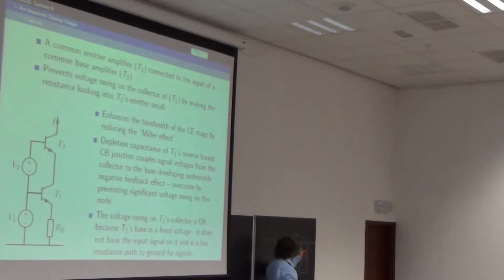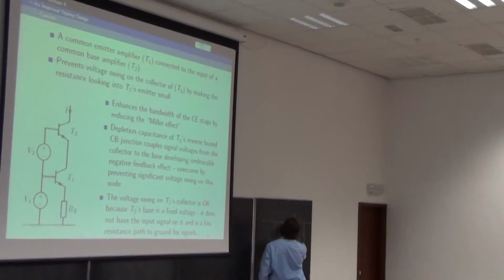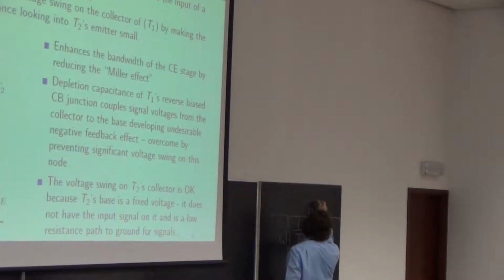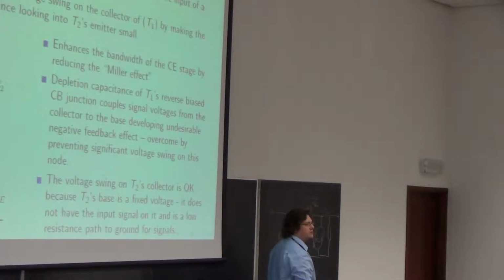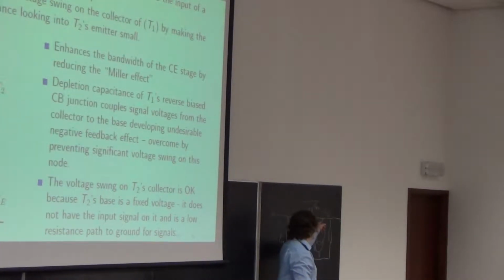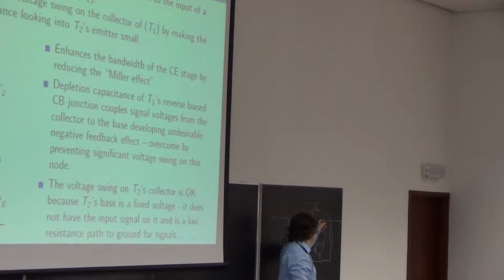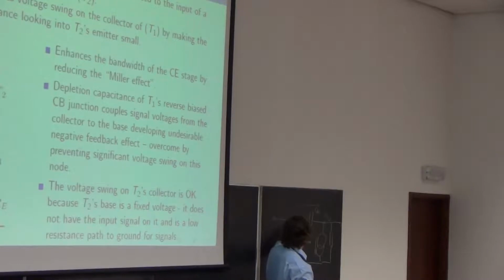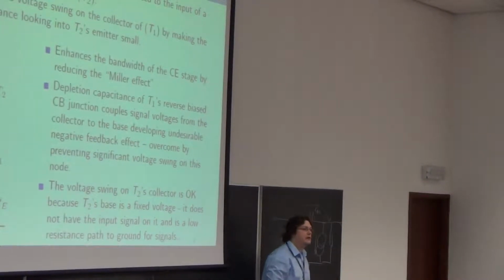If there are no signals here, because there is only a very, very small signal here, if I had a signal voltage here, I could say, well, in terms of signals, this is minuscule, very tiny. So all the voltage across CCB is due to the output, the collector swing. In that case, the signal voltage that's swinging at the collector will drive a current through CBC, which will interact with our base current, and it actually interacts in a way to make this signal current smaller, and that lowers the gain of the amplifier.